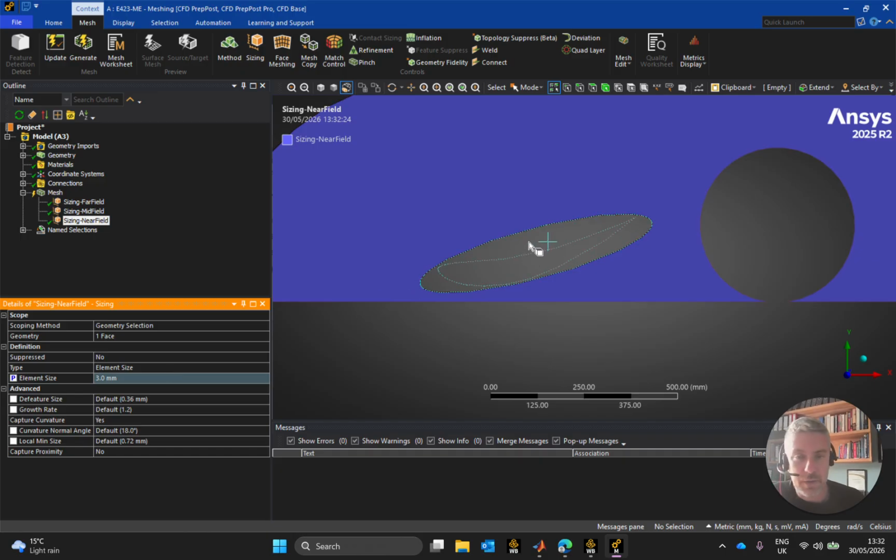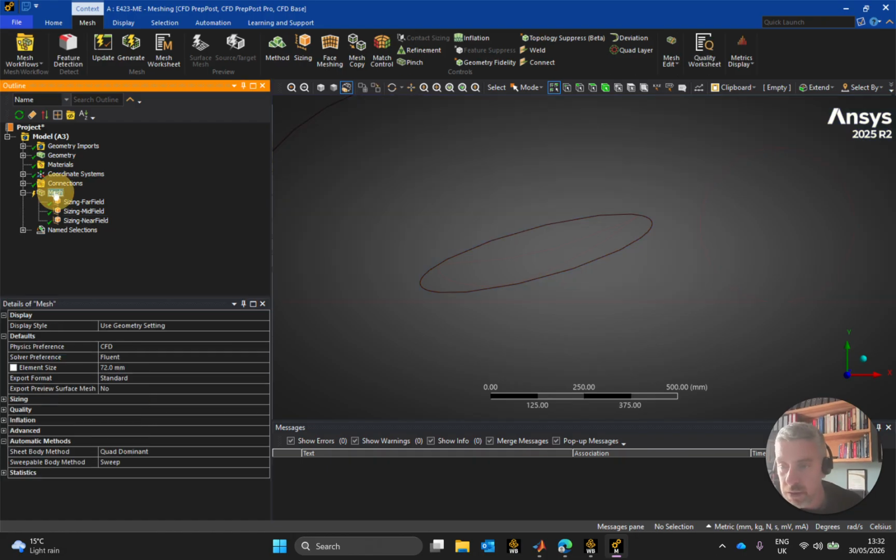We're going to have to use the computational effort if we want the ability to resolve these over small increments. Now, what I'm saying is, if we wanted to change the angle of attack by 2 degrees every time, we can likely get away with a much coarser mesh. But if you're looking only at half degree increments, you need to be careful of that. All right, let's go for the next one.